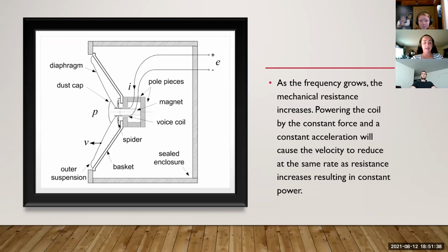A traditional loudspeaker is equipped with a suspension, which is normally made up of both a surround attached to the outer edge of the diaphragm and a spider attached to the voice coil. The purpose of the suspension is to center the voice coil in the air gap and allow the diaphragm to perform the required axial movement while avoiding lateral movement or swaying.